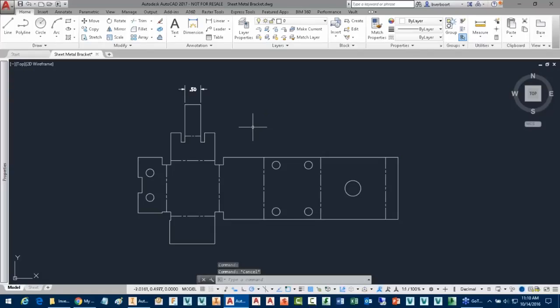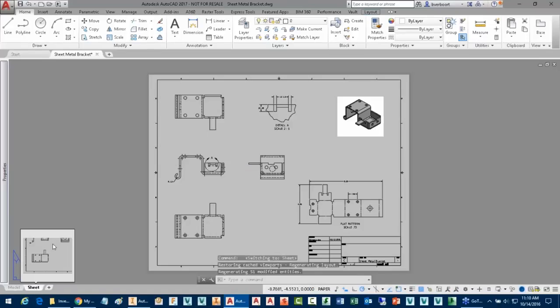So one of the things to keep in mind in this case, there are a couple, I wouldn't call them limitations, but they're just things that you wouldn't want to do here. You wouldn't want to go about the business of modifying this 2D AutoCAD block and expect it to update the drawing view, and then as a result in Inventor update the model as well. So it's kind of a one-way street. We're getting the information out for consumers in this way. Any change you'd want to make would be to the other model, or to the model in Inventor.